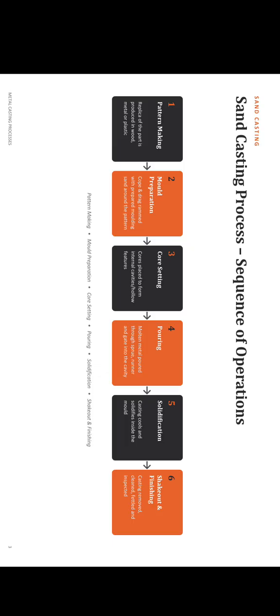Pattern making: a reusable part is produced in wood, metal or plastic. Mold preparation: the cope and drag are rammed with the prepared molding sand around the pattern.